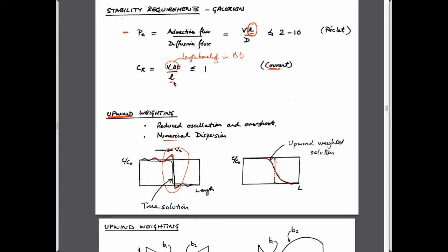If you have problems, if you're right on the edge of stability, both in terms of the spatial stability and Courant number, in terms of having Peclet numbers and Courant numbers that are around 1, then if you make a finer grid to reduce the Peclet number, say you make it 10 times finer, so you have a Peclet number of 0.1, which is fine, then all of a sudden the Courant number will go to being 10, and you'd have to reduce the time step by a factor of 10 or by a factor of 100 to get it down to a fraction of 0.1. And so they work against each other in that regard.